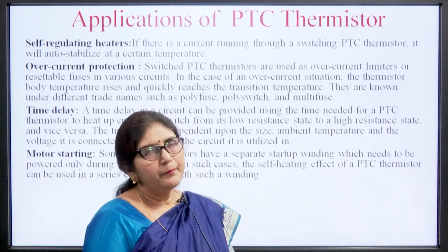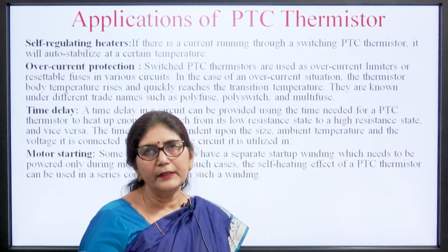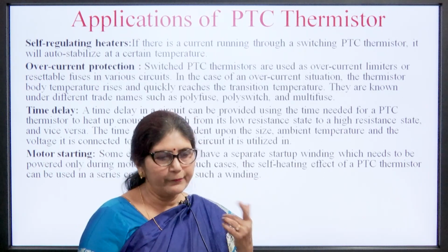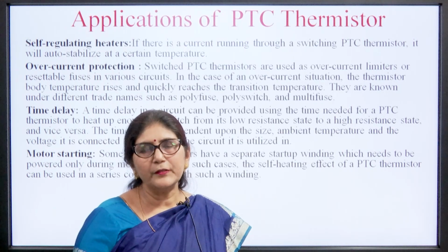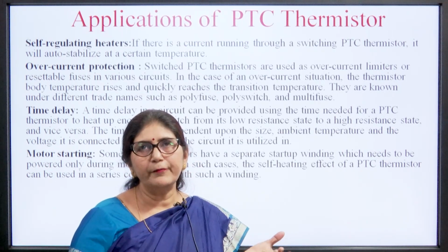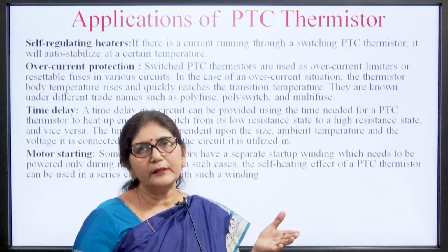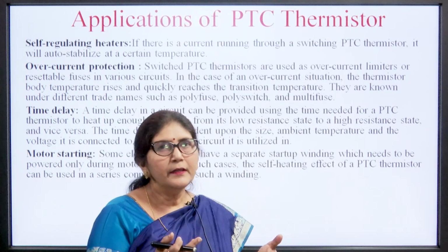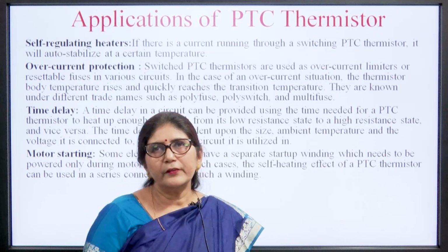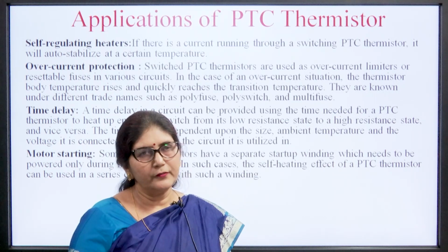Then what are the different applications of PTC? PTC we use for the self regulating heater. We use the thermistor at our home in refrigeration. We are using the thermistors for the geyser. In the microwave we are using the self heating thermistors. So, we know that when current is flowing through the thermistor and it gets heated, then it regulates the temperature. If there is a current running through a switching PTC, it will auto stabilize at a certain temperature.